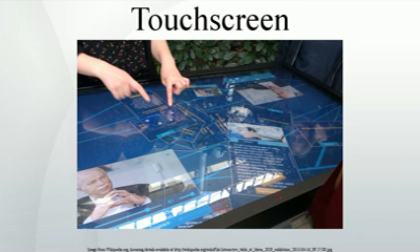Placing a finger near fringing electric fields adds conductive surface area to the capacitive system. The additional charge storage capacity added by the finger is known as finger capacitance, CF. The capacitance of the sensor without a finger present is denoted as CP in this article, which stands for parasitic capacitance.